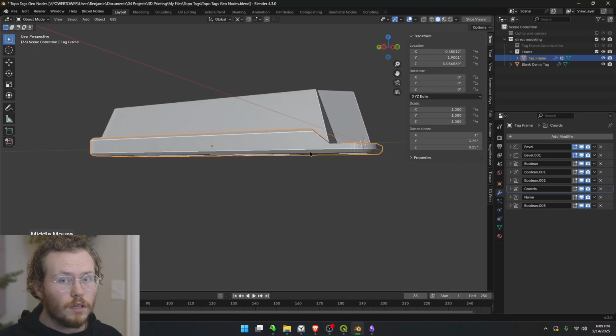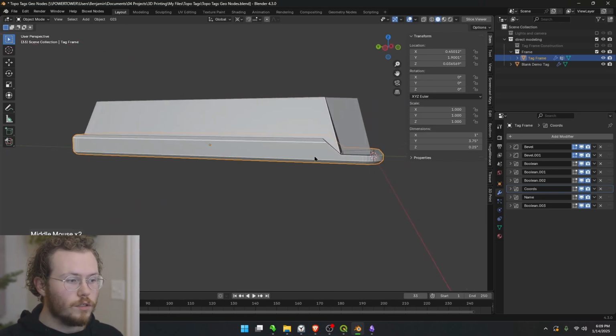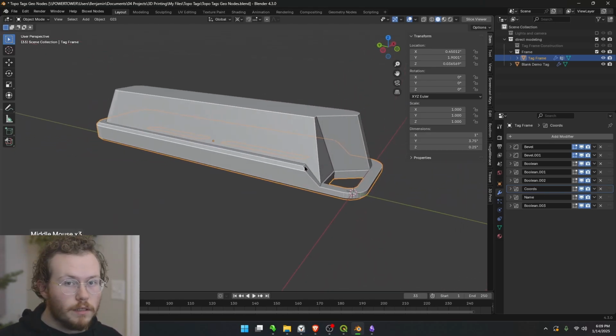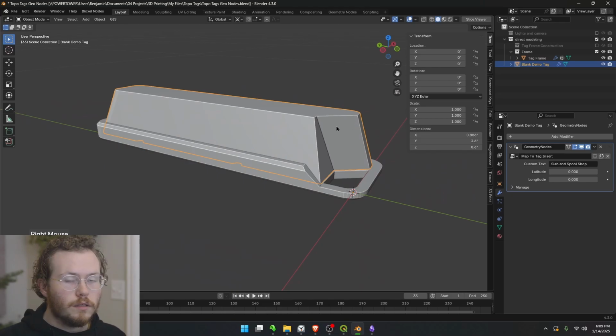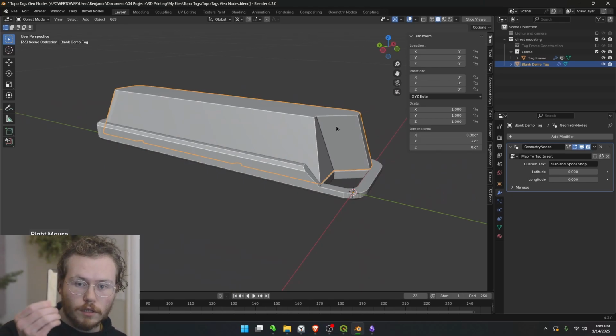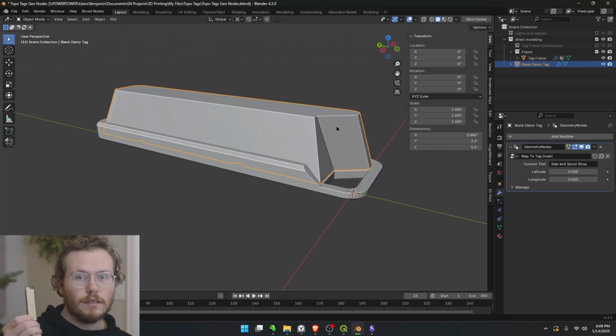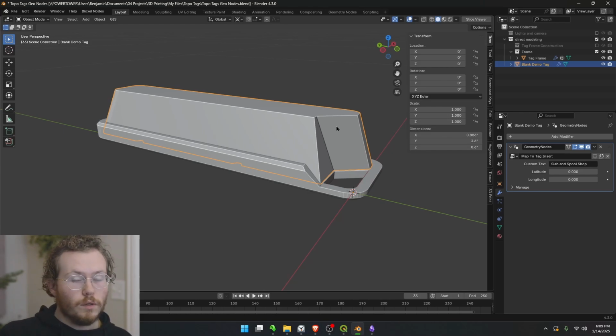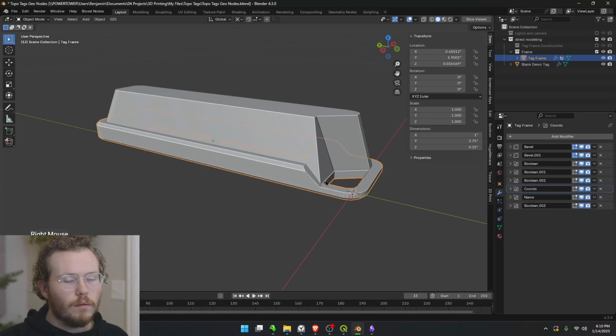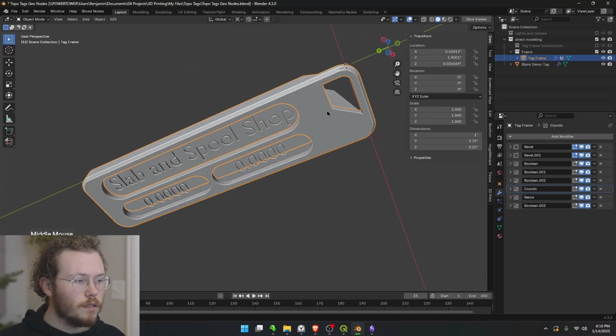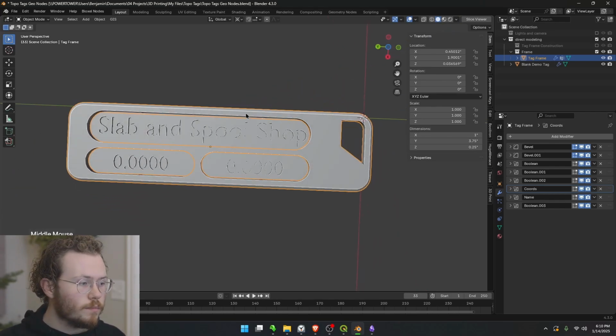You can also use a thicker layer resolution, so maybe it's not a big deal with the resolutions I've been printing here, where they're 0.16 and they don't take that long. But if you wanted to go to even higher detail, it's going to take a lot longer to print every single piece in that. So printing these at a relatively thick layer height, as well as out of more durable plastic, has some benefits.